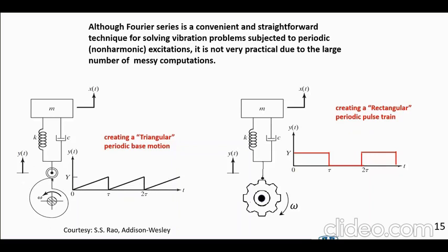This is not the force, but the displacement, okay, on this mass. If your cam actually looked like that, with sharp drops here, literally you can't have sharp infinite drops, there's always an angle, there's always a corner here, etc. But if you had it close to this sharp drop, then it's going to create these pulses, okay? So this is a periodic function. This is a period. If you want to know the response of this mass under this cam, you have no choice but to do a Fourier series of these functions.